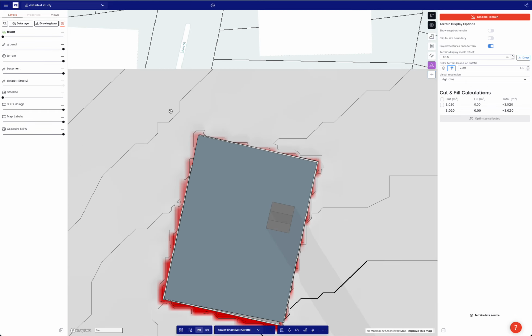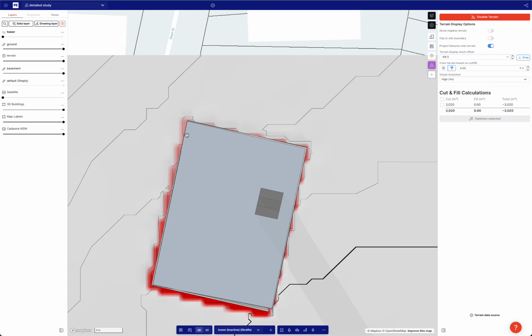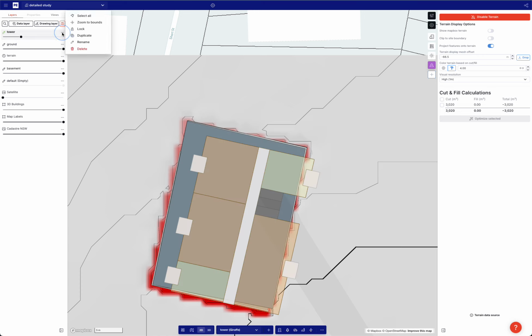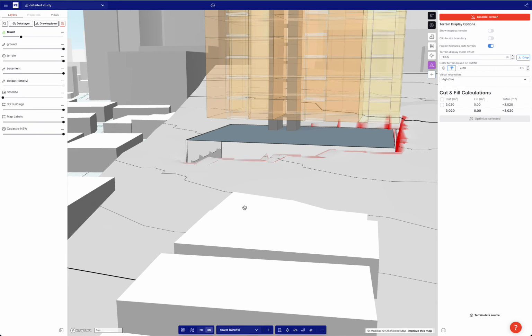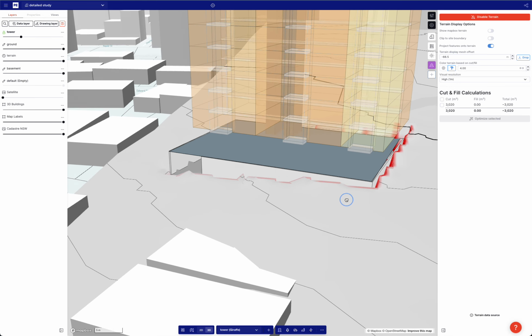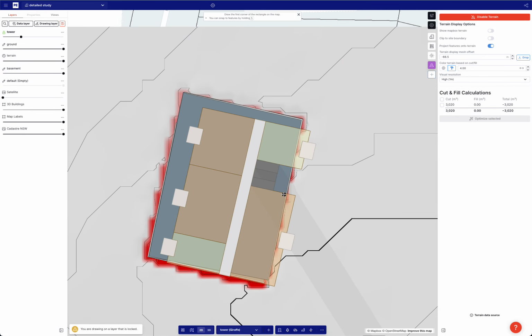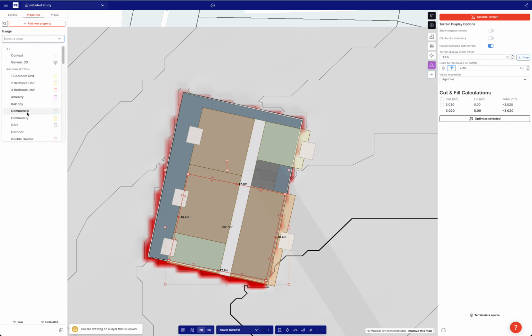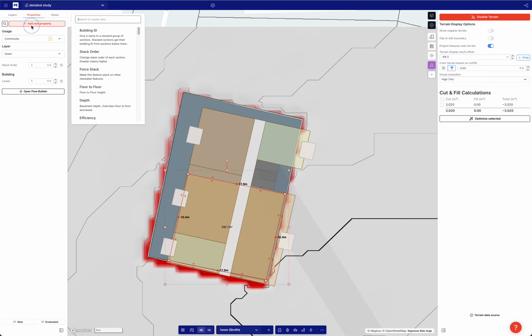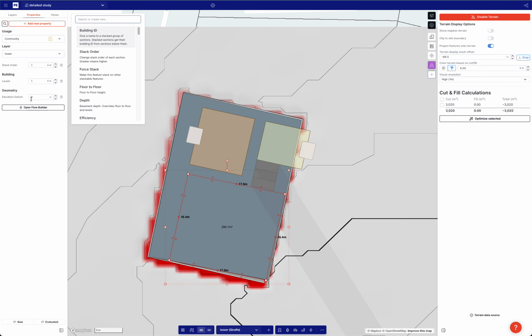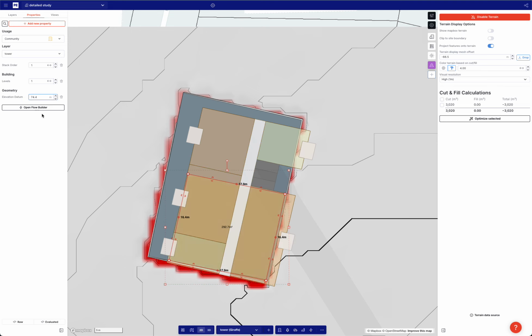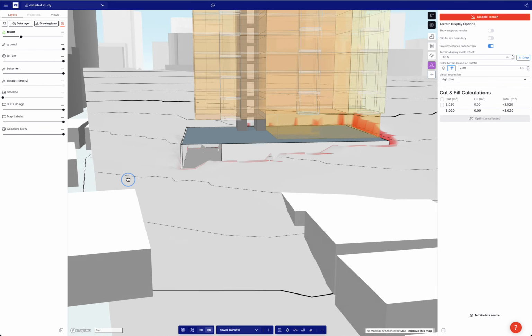And now let's model out on ground that layout. So I would just show it, ghost it in and lock it. And so what I'll do is, this is a terrible plan, it's so silly. But anyway, I'm just assuming that I've got it right. So let's say the lobby is going to be a big cafe lobby. So I'm just going to draw a rectangle and set that usage to community and set that elevation datum to 74.4, which is our base datum. Okay, so there's that sort of thing.